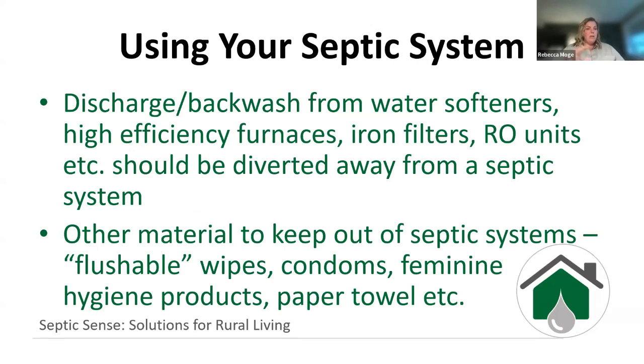Those people who are installing these for us should not be attaching them to our septic system. They should be pumped out elsewhere. So a French drain or a dry well is where those want to be discharged. We don't want that going into the septic system and, again, overloading our system. We want to make sure that it's not backwashing more than it needs to be. So looking at the manufacturer's specifications, sometimes when they're installed, they're just installed and away we go, and it's kind of set to a higher setting. So we can look at that and make sure that it's not backwashing more frequently than it needs to.